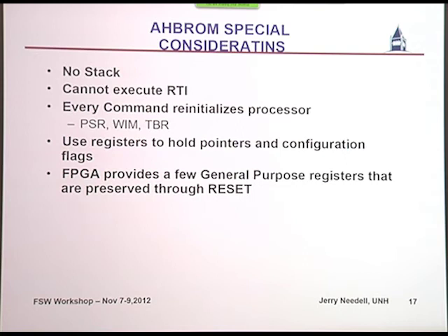You don't forget everything on every start, but you can pass a few pieces of information along. The FPGA developer provided a few extra registers that are very helpful in the system to allow us to store some parameters that are preserved through a reset. So it gives us a little extra working space in the memory inside the FPGA.